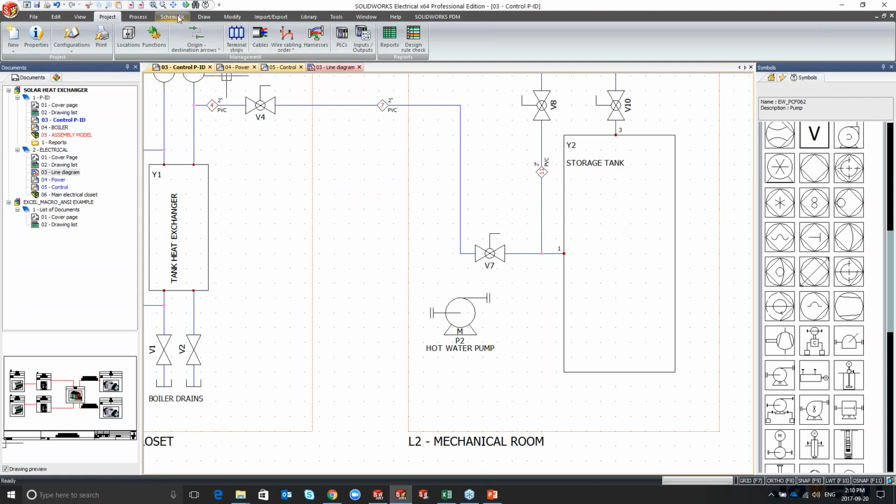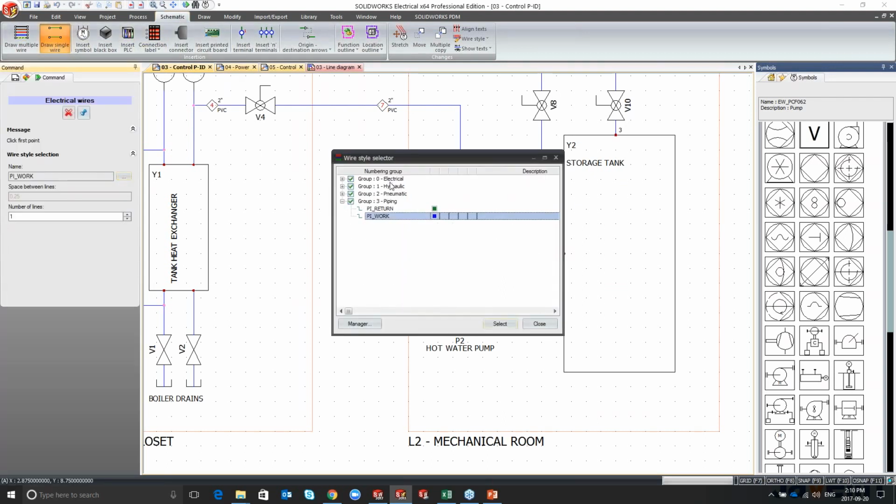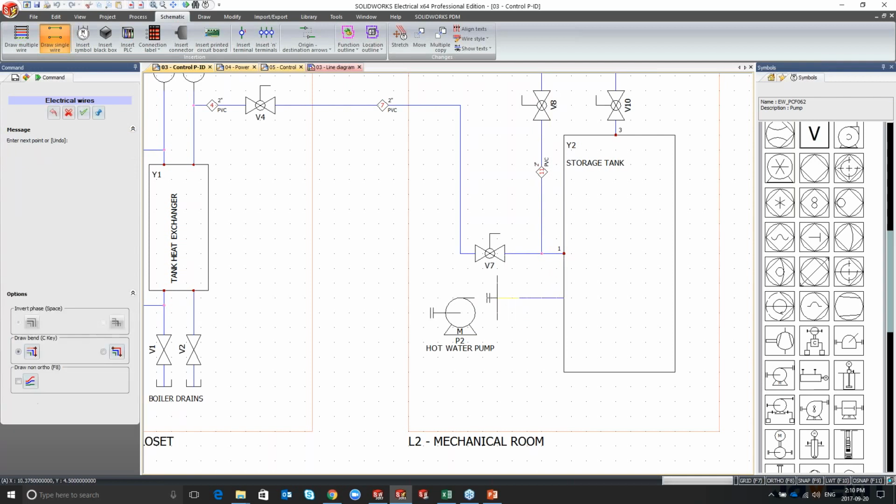To make pipe connections, I'm going to borrow some of the product's existing features and start making connections. So I have the option of picking electrical, hydraulic, pneumatic, or piping. I've picked the piping segment. I'm going to use a working line, and I'm going to draw right through.